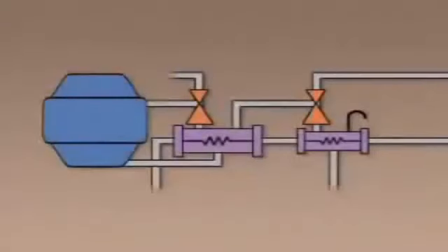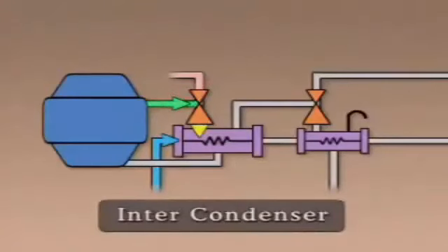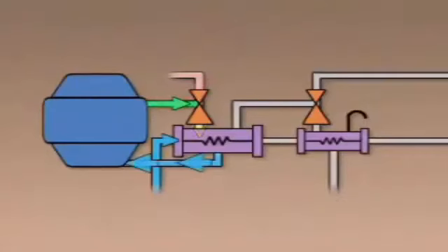As shown in this illustration, a 2-stage air ejector arrangement creates a greater vacuum than a single air ejector, resulting in improved condenser efficiency. In this system, steam flow through the first air ejector draws in air from the main condenser. After the air combines with a jet of steam in the air ejector, the steam-air mixture flows into the shell of a condenser, which is often referred to as an intercondenser. There, the steam condenses and drains back to the main condenser, while the air flows into the second-stage air ejector.